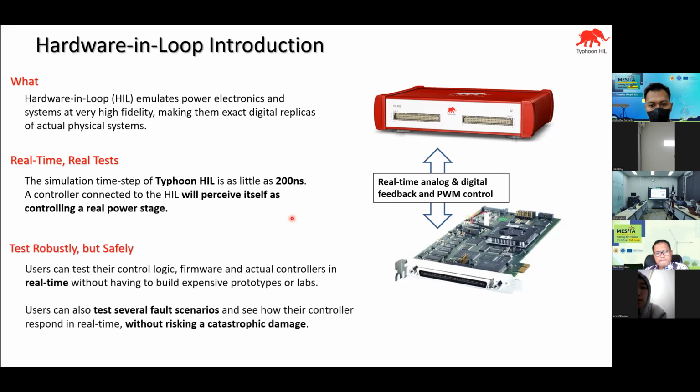Because of that, you are able to test your control logic, your firmware, and your actual controller in real time without having to build expensive prototypes or labs. Also, you can design different fault scenarios and see how your controller responds in real time without risking catastrophic damage.